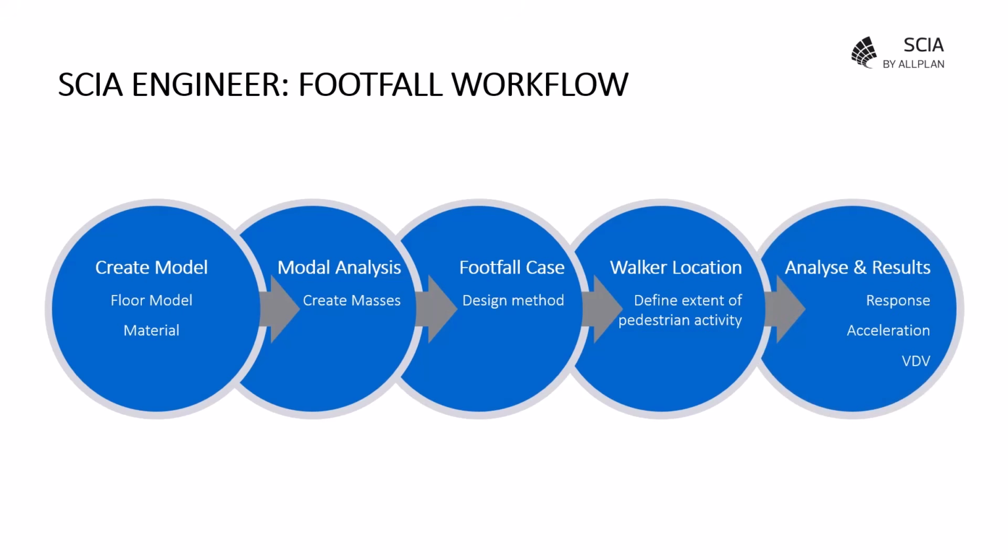Finally, you run the analysis and review the results. At this point, you can make more informed and targeted design decisions. For example, adding extra members to critical areas or maybe additional mass. These types of changes will have the most significant effect on the vibration response.